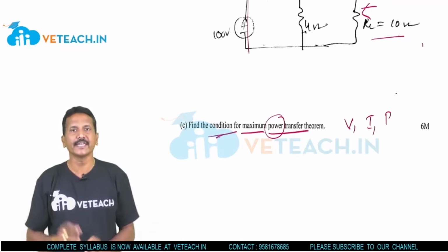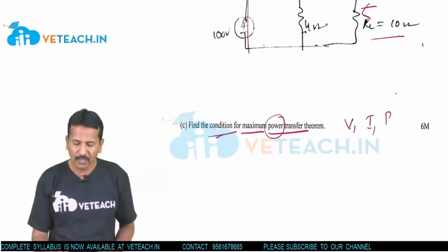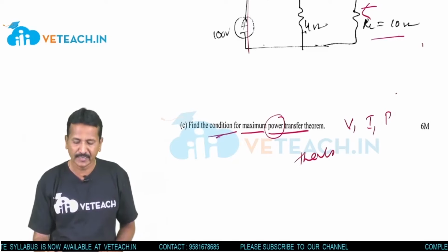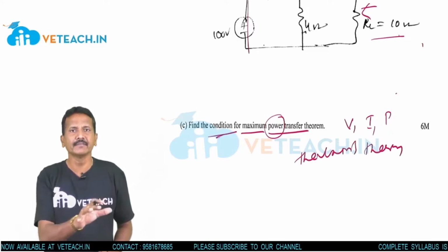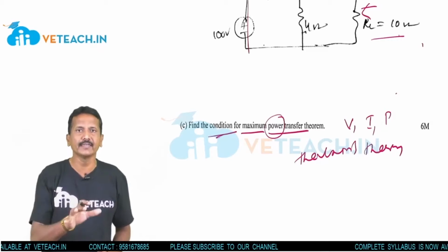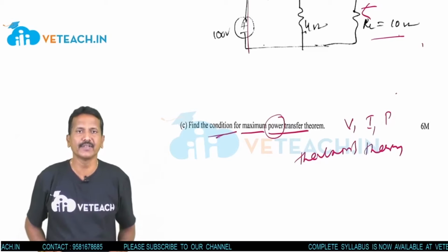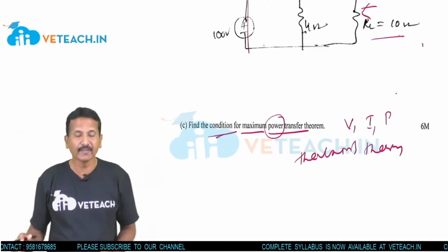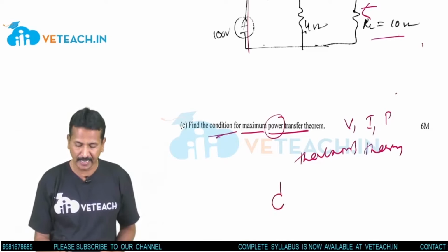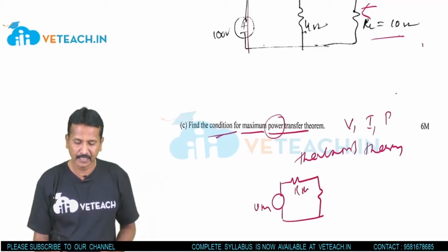Okay. So one thing here, maximum power transfer theorem is 80% dependent upon Thevenin's theorem. Same steps. Network given, open the load resistance, find the Thevenin voltage VTH, short the source, find the Thevenin resistance and draw the equivalent circuit diagram. Right? Now this is the point here. This is VTH, this is RTH and this is RL, this is IL.